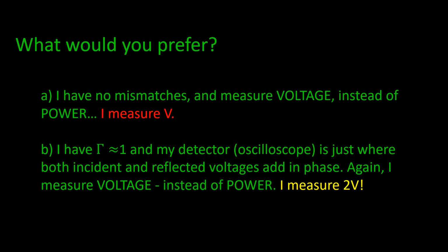On the other hand, your detector, I mean the oscilloscope, measures voltage, and it is located just at the place in which the reflected voltage and the incident one are in phase. This leads to a total voltage that is around 2 times the incident one, so you are indeed taking benefit of this reflection. Actually, a number of sensitive detectors use this effect.